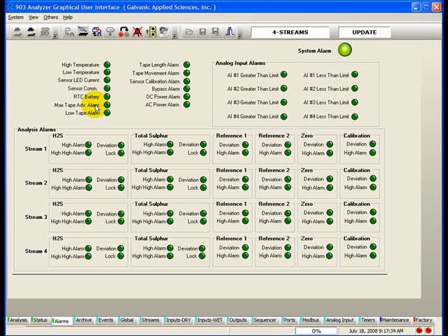Maximum tape advance will be triggered if the motor advances the tape more than a certain number of rotations without getting a corresponding signal from the pulse counter that controls the tape advance. If this alarm triggers, it will generally indicate a problem with the encoder. The length of the maximum tape advance can be set by the user, but is advised to leave it set